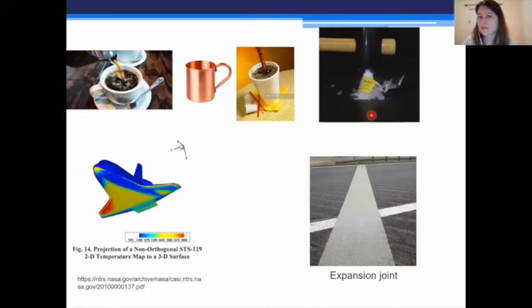The second application on the right of this slide is a plastic bottle, but you can see that this plastic container seems to be very brittle. And so in fact, in this case, this plastic bottle has been cooled down below a certain temperature that we already presented, which is the glassy transition temperature. And so below this temperature, the polymer is brittle, and so if you apply a stress on it, a force on it, you can observe that it is breaking.